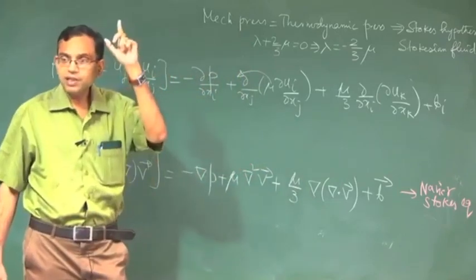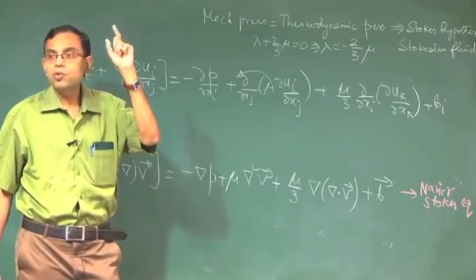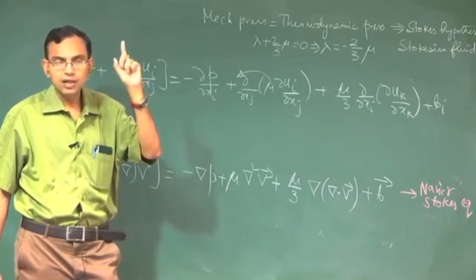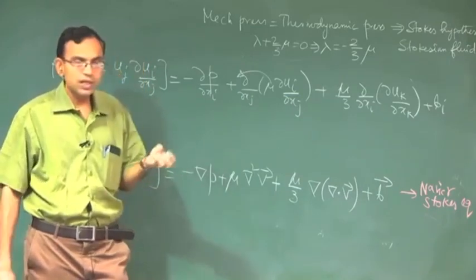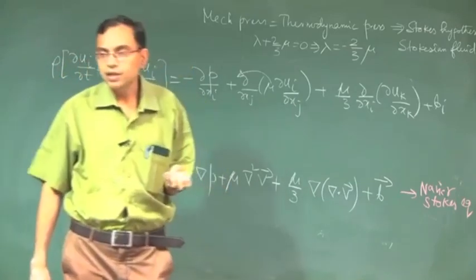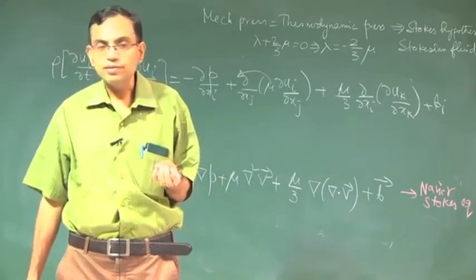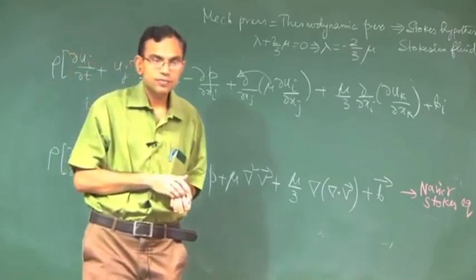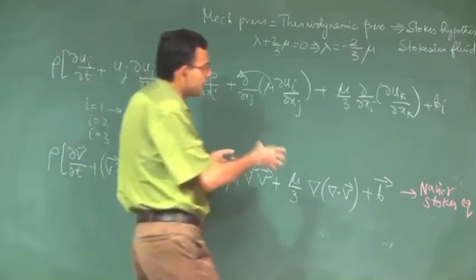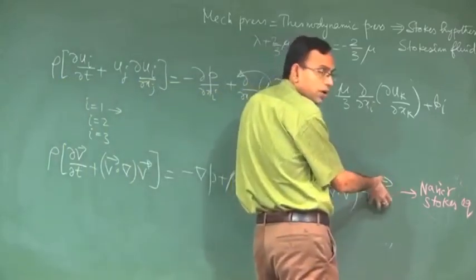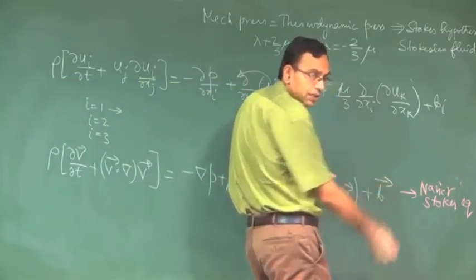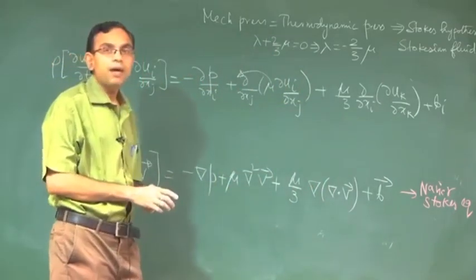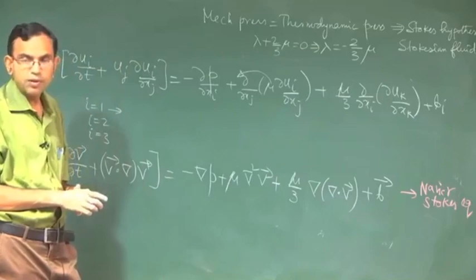The first assumption, keep in mind, is that there is no body couple, the Navier equation, and then homogeneous, isotropic, Newtonian and Stokesian fluid. So these 5 major assumptions, and any other assumption can lead to an additional body force which can be dumped here. Okay. Now let us look into the balance of the number of equations and number of unknowns.